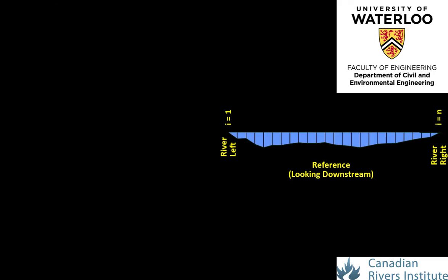For the given cross-section of interest, it should be divided up into approximately 25 to 30 subsections or verticals. Fewer panels can be used if the cross-section is relatively uniform. As long as one roughly maintains the recommended number of subsections, the choice in the specific spacing is commonly based upon the convenience of the measurement by the user. For instance, spacings of 0.5, 1, 2, or 5 meter intervals are easy values to enumerate and follow during the field measurement process, rather than multiples, for instance, 0.63 or 11.29, for example.